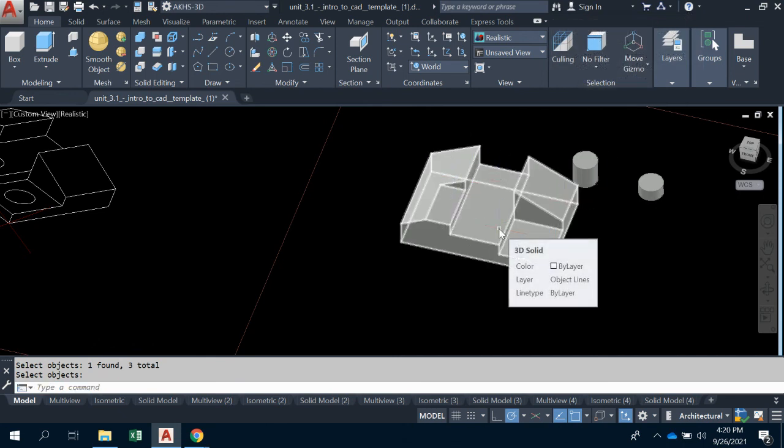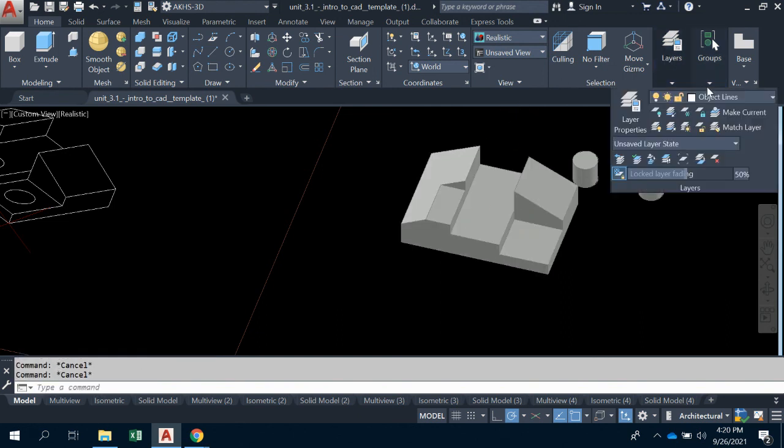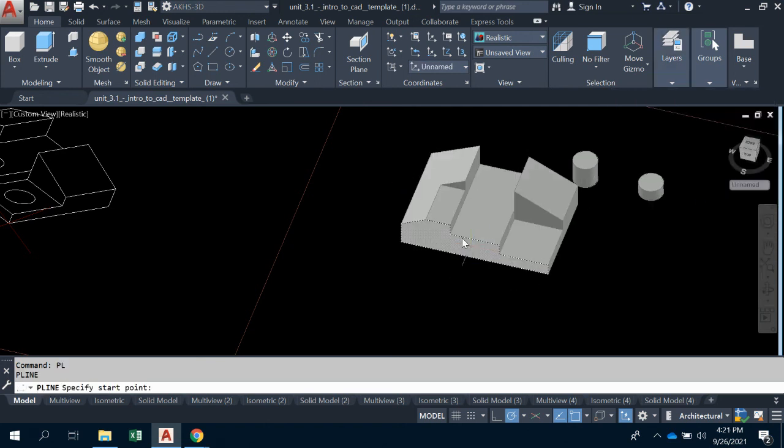And then we're going to draw a line so we can place these where they go. So I'm going to do a polyline, but make sure you're in a construction line first so you can see it. So a polyline, and then I'm going to go from this corner in 0.5, and then I'm going to come up 0.5 as well. And then I'm going to repeat that here, 0.5. You could also snap to the midpoint, and then come 0.5 this way as well.